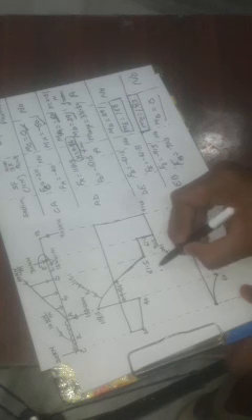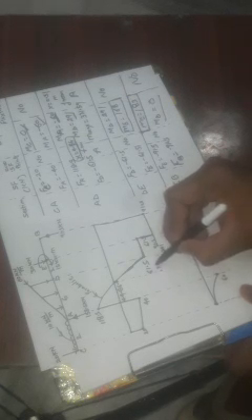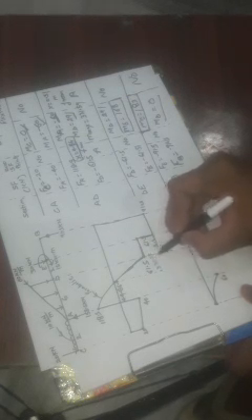Then we will make a dotted line from X equal to 4.86 and say this value is 331.59. The variation here will be cubic, one power ahead of parabolic. Draw the cubic variation: start from this point, it moves up to here, then comes down like this. This is the maximum value of the bending moment, 331.59.